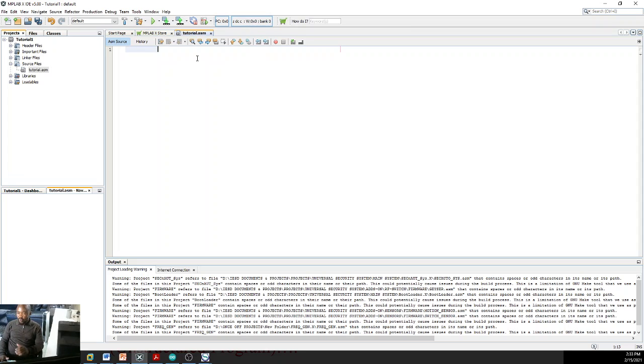You need to tell the compiler which PIC microcontroller you are writing a program for, and you do that by using the list instruction. List P equals 16F84A. That's how you inform your compiler that you are writing a program for this particular microcontroller. List P equals 16F84A. Now, this next instruction is also very important. I will explain the purpose of this instruction later on.